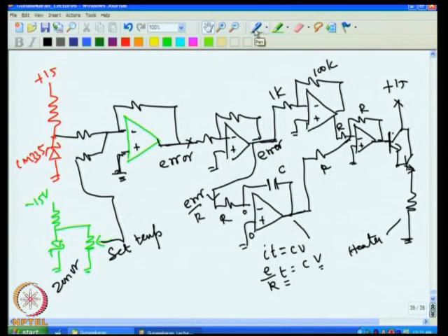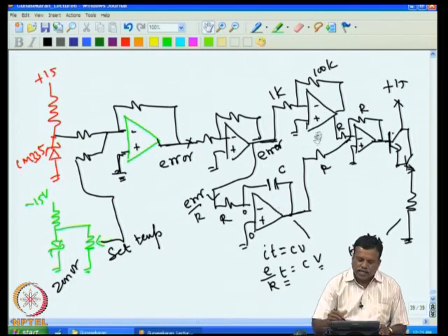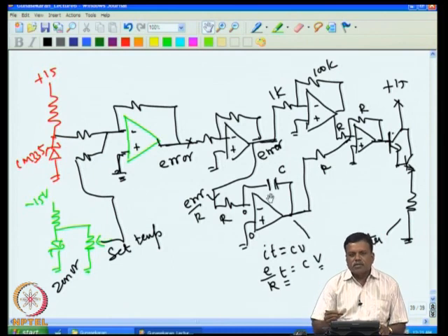So the integrator was a good invention, but then we always get confused, because the integrator is there. Of course, I can reduce the gain substantially, because even if the gain is lower, the error is not going to be there at all, because integral action is there, that will take care. But one has to set correctly the required gain, and then the required time constant for the integrator.